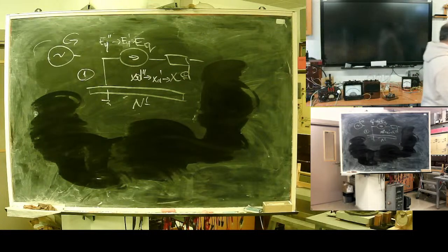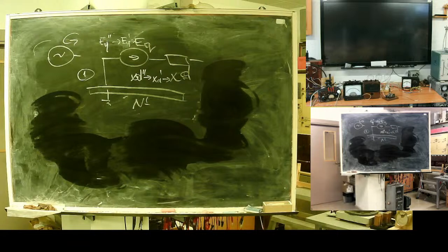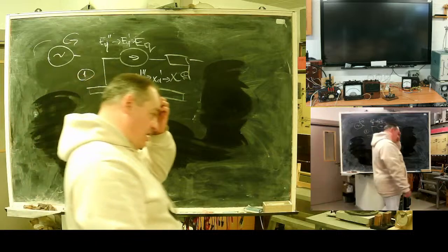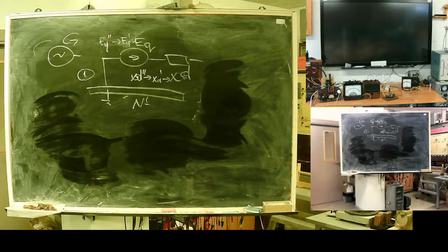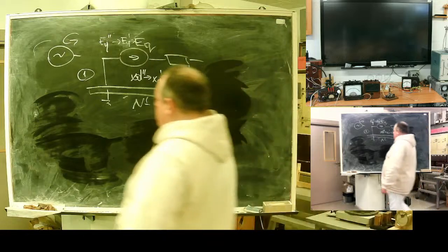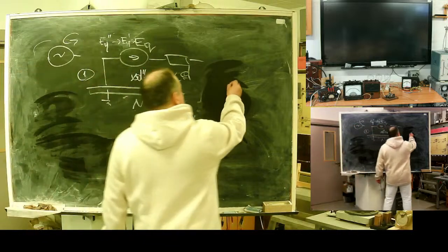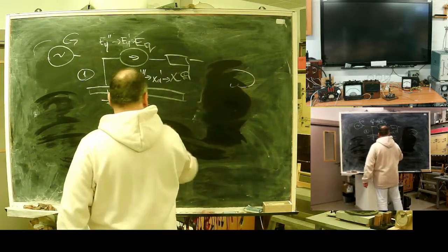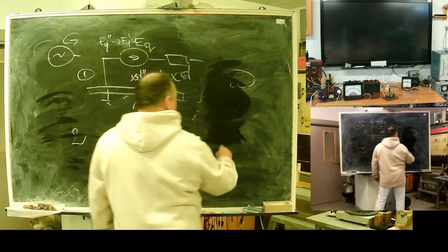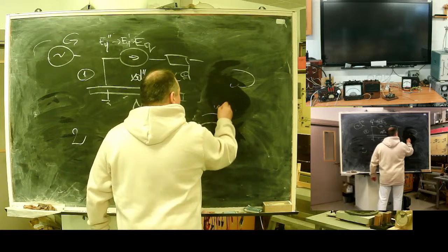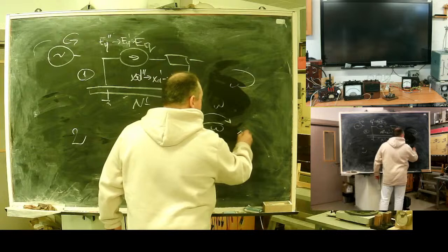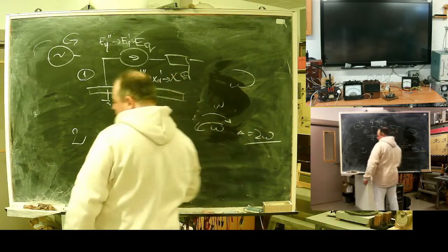Much depends on the presence of damping winding. For the magnetic field of negative sequence, our machine rotates in the counter direction. If in direct sequence the machine has speed omega, in negative sequence the difference equals double omega.